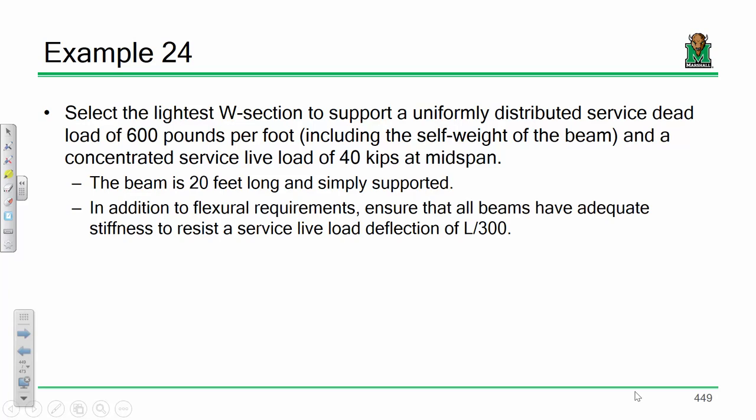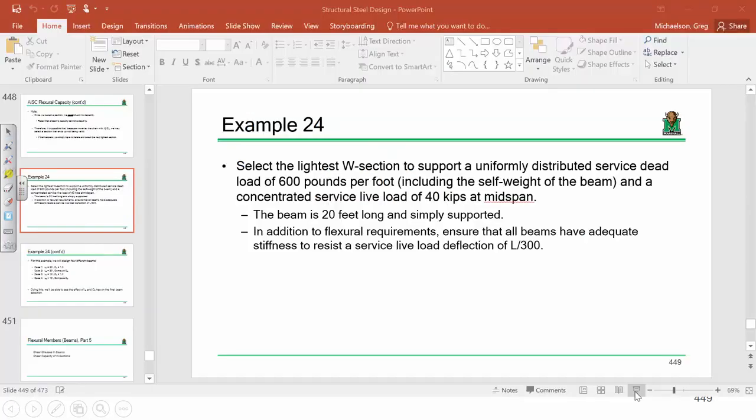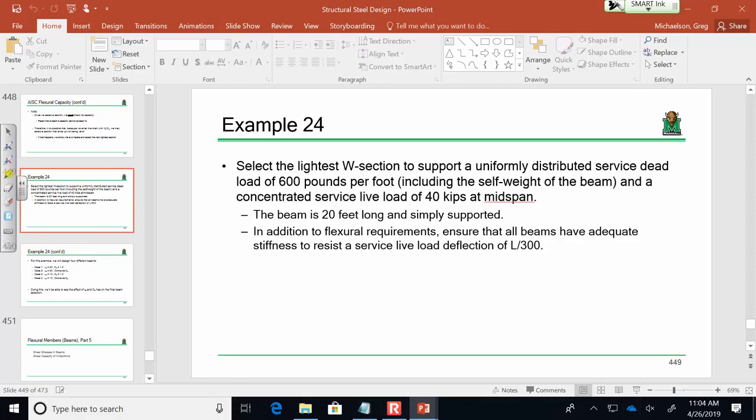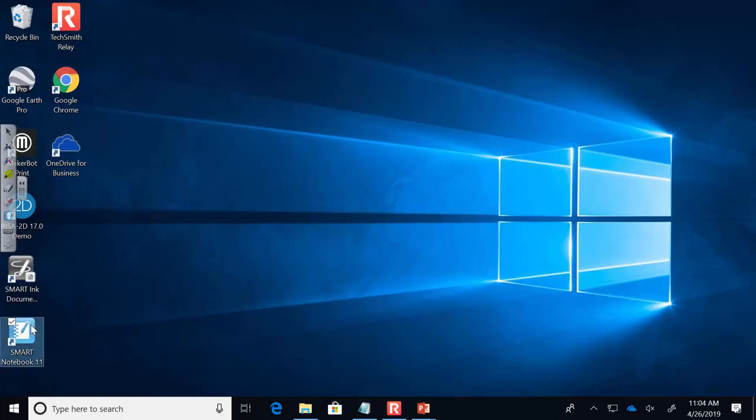I can go ahead and tell you that for all of the 4 cases that we designed, shear is not going to be a big deal. We are going to meet shear demand by a mile. That's not going to be an issue. Moment is going to be the one that we're primarily fixed on, and deflection is something we're going to have to check at the end. So let's just get right into it.